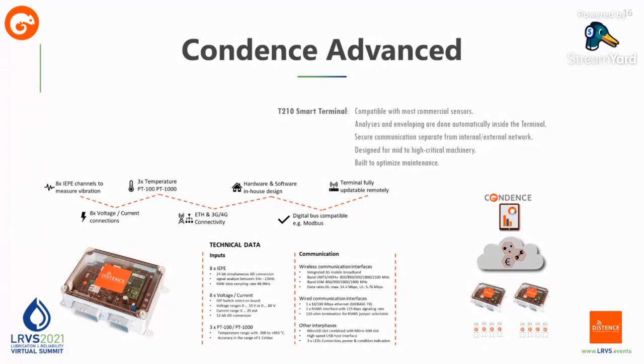During every calculation cycle, where we look at the data from many different angles, well over 550 calculations and envelopings are automatically executed on site inside the edge terminal. We simply introduced a few new ones to the pile that, instead of vibration, focus on friction. Simply put, increased friction indicates decreased lubrication effectiveness.